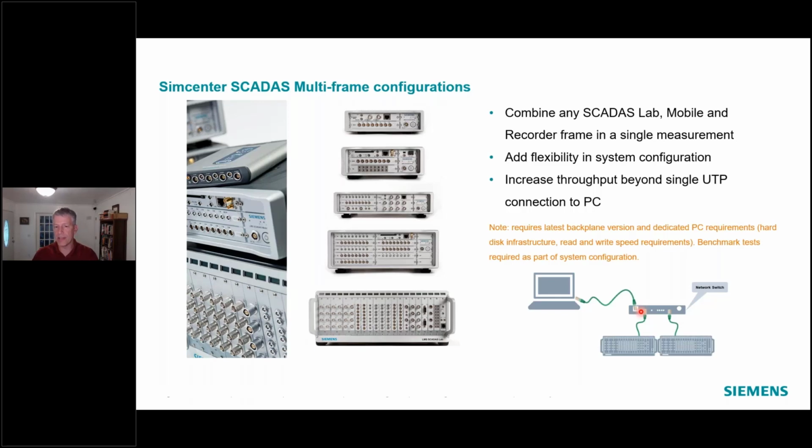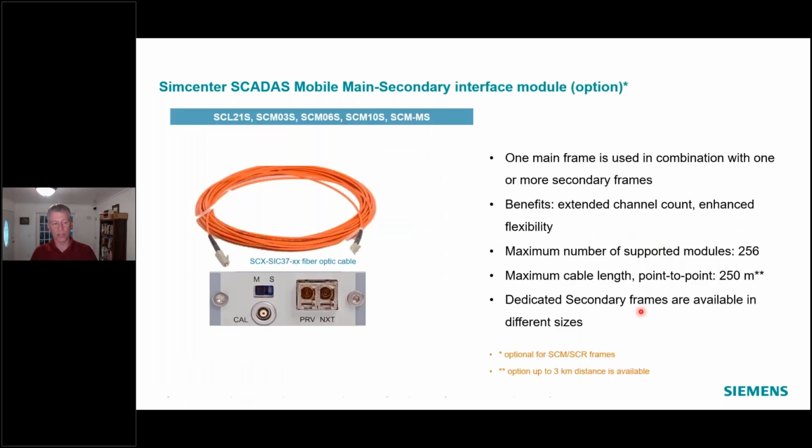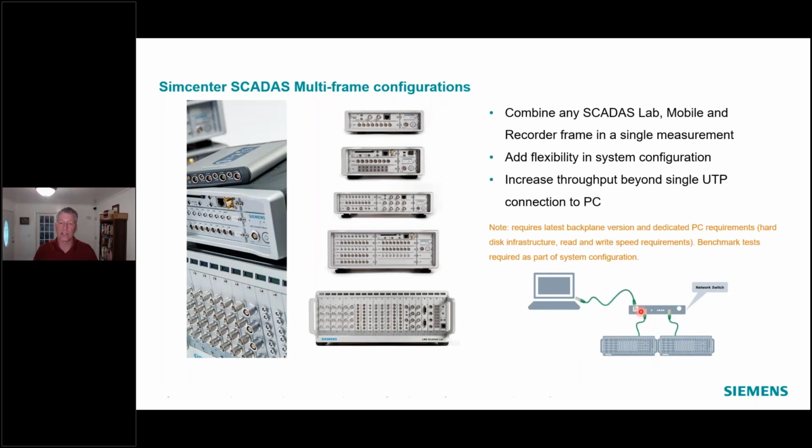So this gives me higher bandwidth capabilities than the main secondary approach that I talked about previously. In this case, using the fiber optic connection, I'm still limited to the single frame connection speed of 19 megasamples or 14 megasamples. Using this network switch connection approach, I can actually go higher than that, where I still have a single computer, but then I can get into like 38 or 40 or even 50 megasamples per second, depending on the architecture and connection.